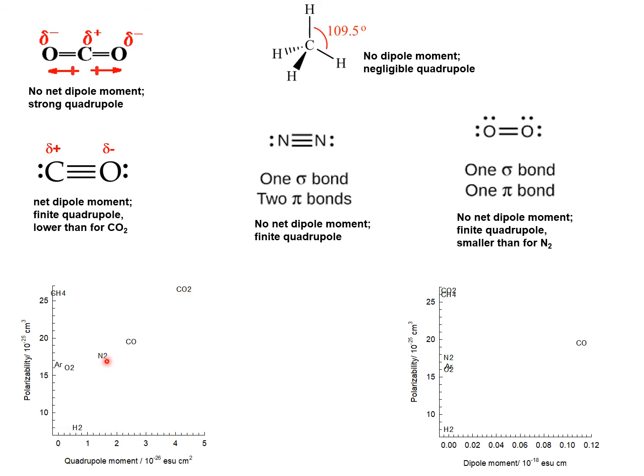Similarly, the selective adsorption of nitrogen from mixtures with oxygen is achieved because of the large quadrupole moment of nitrogen that is 4 times larger than that of oxygen. For CO2 capture from flue gases, we rely on the large differences between the quadrupole moments of CO2 and nitrogen. And also the polarizability of CO2 is higher than that of nitrogen.